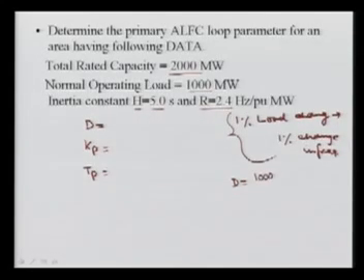here 1000 of 1%, that is 1 over 100, and this is in megawatt, divided by 1% change in the frequency. A 1% change in frequency means your system frequency is 50, and 1% of that is 0.5, and this value is coming out in megawatt per hertz. The unit here, be very, very careful.